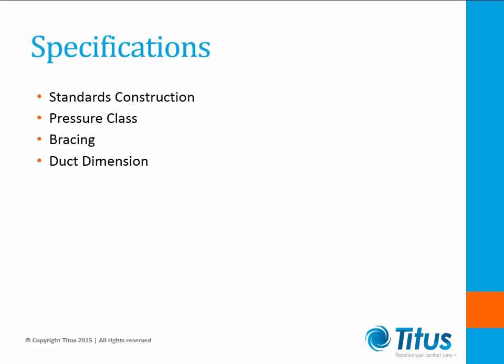So it's always a good idea to set your system static pressure class by the maximum available and not the design point. In duct construction standards, there are multiple methods for bracing and connecting ductwork sections. Each of these methods has a different height above the ductwork that should be considered in system clearance calculations earlier.